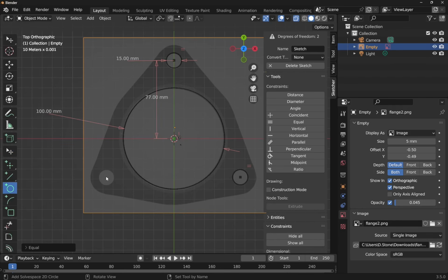Let's just add a circle in here. It's just as easy to create a circle. Right click to get the mouse pointer back and click one, shift click the other and make those equal. Got the circles in? Well, we need to keep this point and this point in line. Shift click those 2 points. Got a horizontal constraint in.